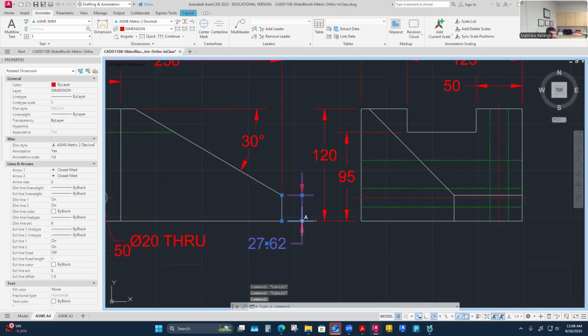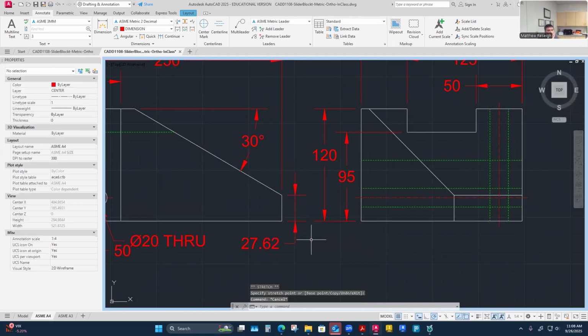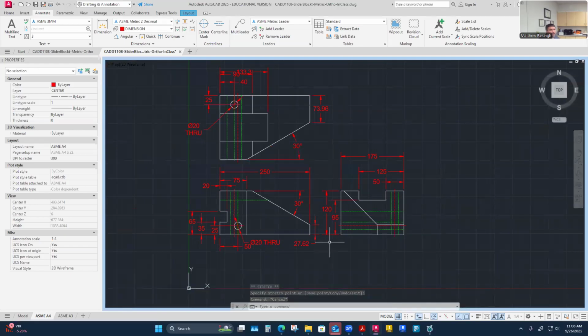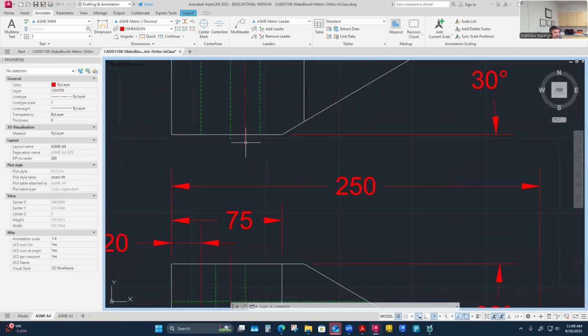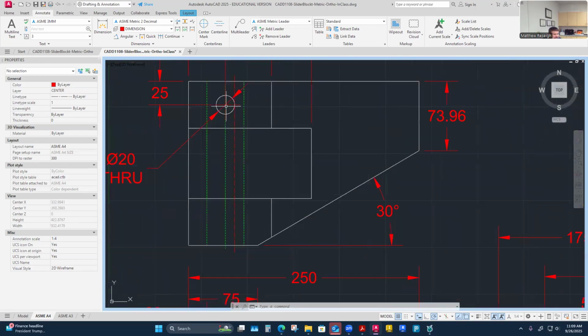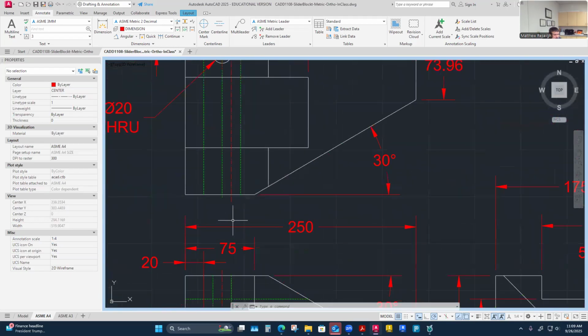Yeah, go ahead, have a go. I did it the long way. Can you connect to the center line, or is that not any kind of dimension? No, you can dimension to it, absolutely. A surface to the center line is a legit place to pull from. Your center lines are as good as datums as a surface is, so they're a great place for any dimensioning. I've just used them in the center mark area rather than where they go through. With that, you only get one dimension, and then you have to look at a different view to get the other one, and that's fine.